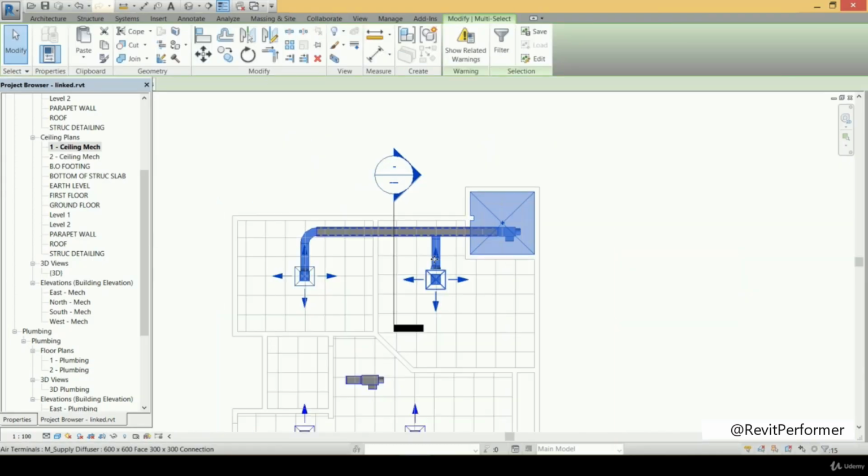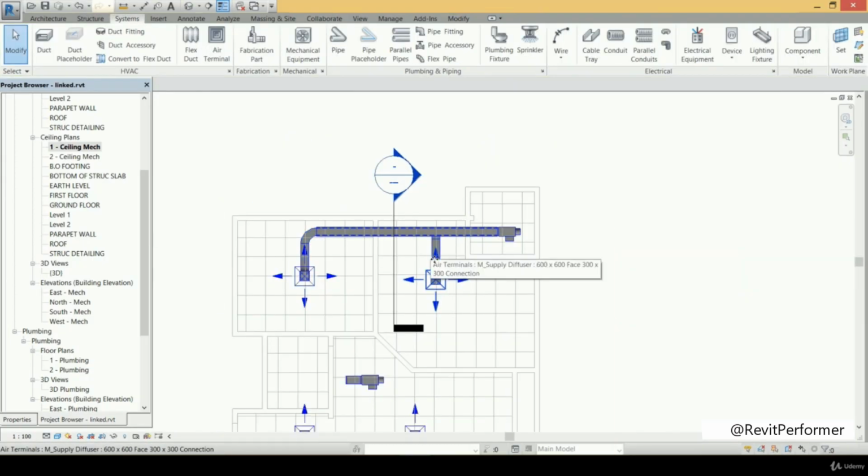And also we have another check which is called the interference check, as it tells us if there is any interference at the ducts we have. For example, two ducts may overlap, so the program can detect that interference. But for that small system, it may not be a problem as we can detect any error with ease, but this will be a problem for the large systems that have complex details of the ducts and the air terminals.